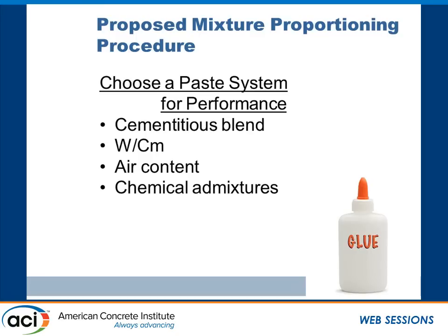We choose our water-cement ratio. At the moment, based on experience in Minnesota and the fun that we're having with joint deterioration, my recommendation is that for pavements in a cold environment, target a 0.4. If you get 0.42, I'm good. If you specify a 4.5 and get a 4.8, you're looking at joint deterioration. Don't come back to me and complain.